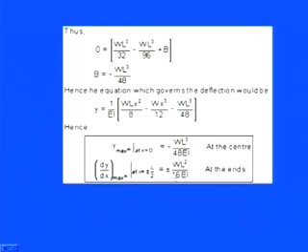So by keeping those values at x equals L by 2, and then if we manipulate those things, we have the final value as plus or minus WL squared by 16 EI. So the meaning is pretty simple: one can easily get this. It is a very simple method as compared to the